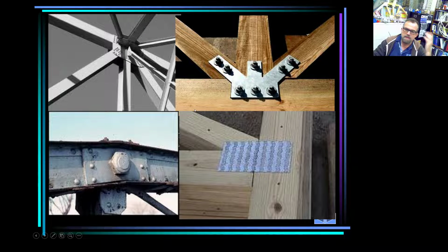And on top of that, remember all the considerations that we have with the loads, and we explained that in previous chapters. The loads are factored, the capacities are reduced. So yes, we can live with these as pins. Why don't we build those as pins? Well, because building perfect pins would be impractical and extremely expensive. And these, for our purposes, will behave like a pin.